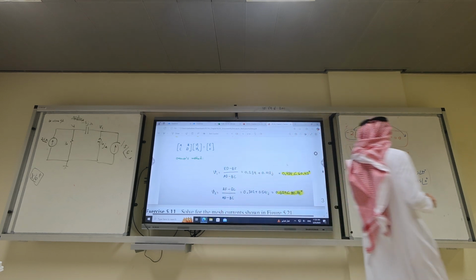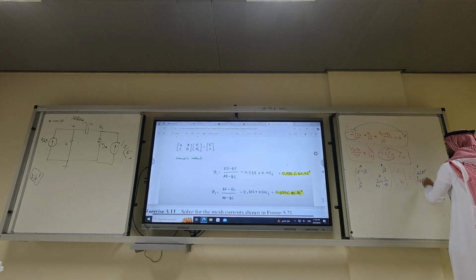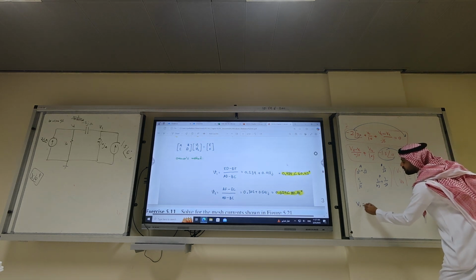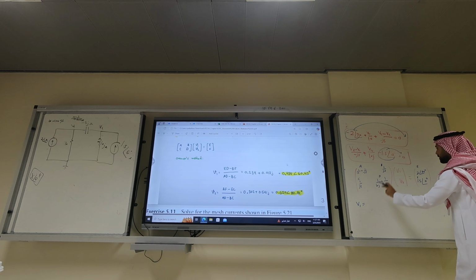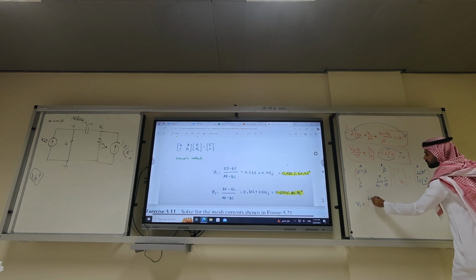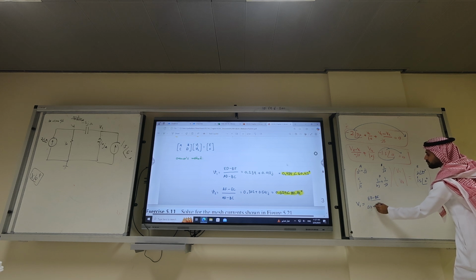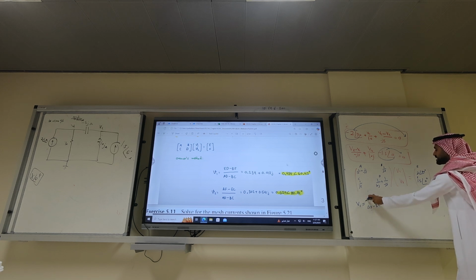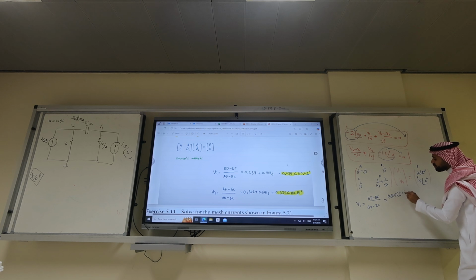So what is A? A, B, C, D, E, F. So what is V1? You put E and F here, so it's going to be ED minus BF over AD minus BC. So what is ED? ED is 2 angle 90 times 1 over 10 plus 1 over minus j5.